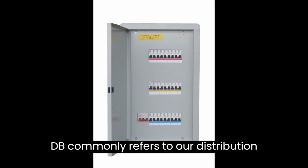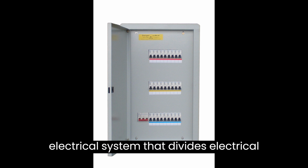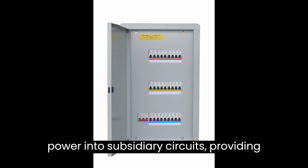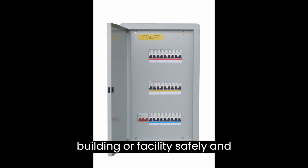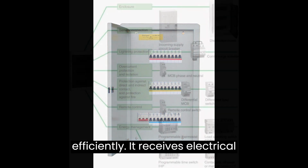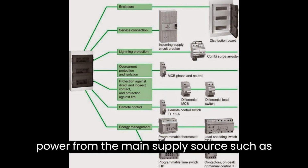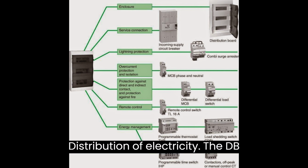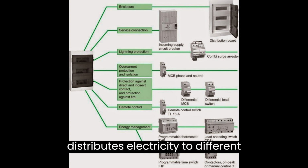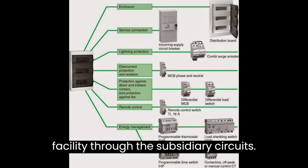DB commonly refers to a distribution board or distribution panel. This is a crucial component in an electrical system that divides electrical power into subsidiary circuits, providing a way to distribute electricity around a building or facility safely and efficiently. It receives electrical power from the main supply source, such as the sub-main distribution board, SMDB. The DB distributes electricity to different areas or sections within a building or facility through the subsidiary circuits.